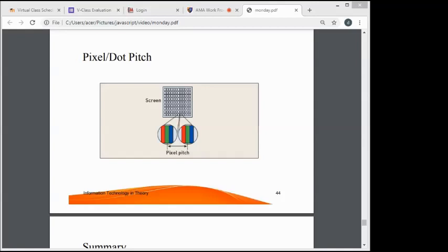Okay? For consumer video standards, the bit depth specifies the number of bits used for each color component. The color depth is only one aspect of color representation, expressing the precision with which the amount of each primary can be expressed. The other aspect is how broad a range of colors can be expressed. The definition of both color precision and the gamut is accomplished with a color encoding specification, which assigns a digital code value to a location in a color space.